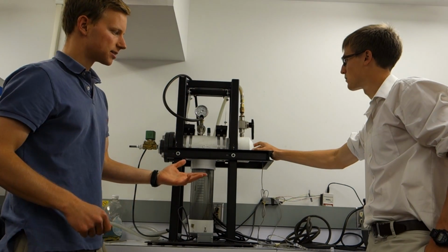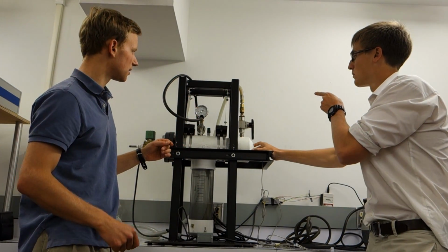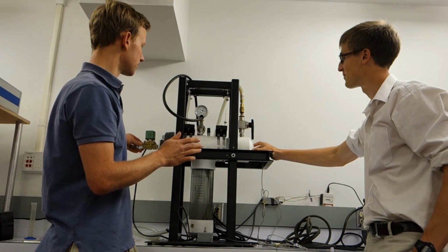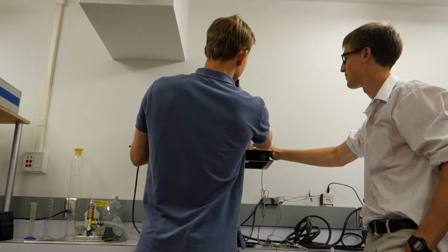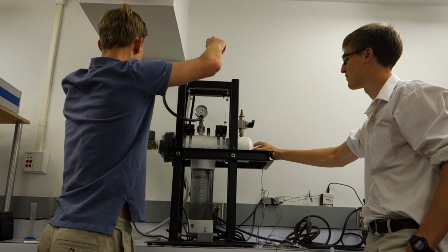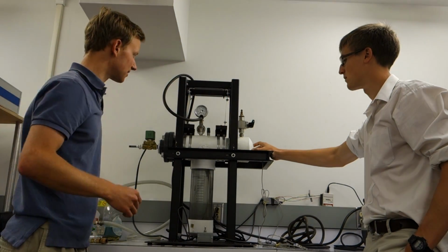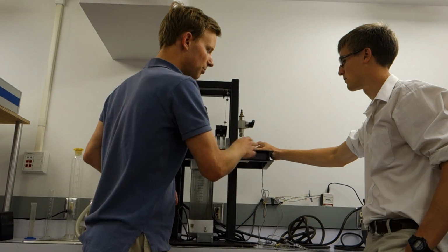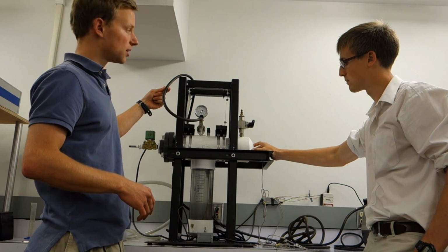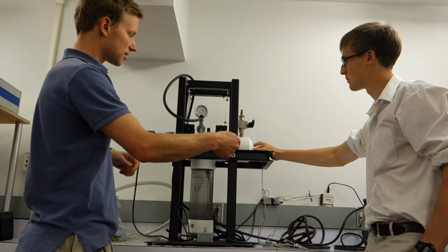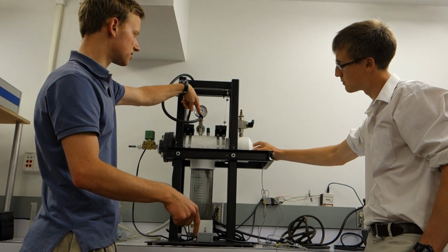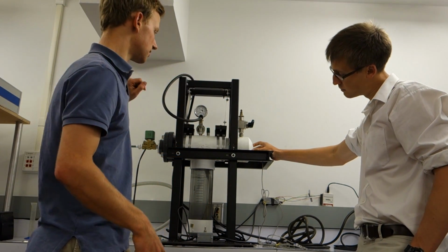and then turn the compressor on. Now this is very important. Oh, right. I also need to take off the water hose so that we don't restrict the motion in the extraction. Thank you, Matt. Close that. Take the hose away. Now I can pressurize the air. If I turn the compressor on and then close the valve after we've got the 40 psi, I'll be compressing the air in the hose, which is dangerous for the hose. So we'll turn the compressor on, wait for it to get above 40 psi, turn the compressor off, and then close the hose for the air hose.